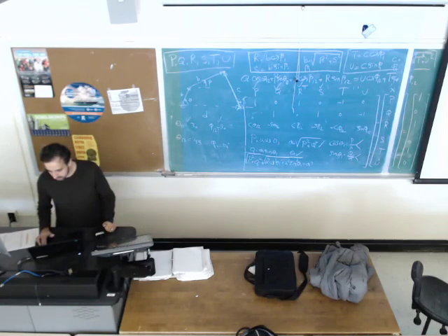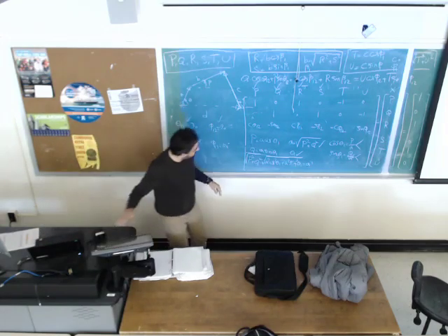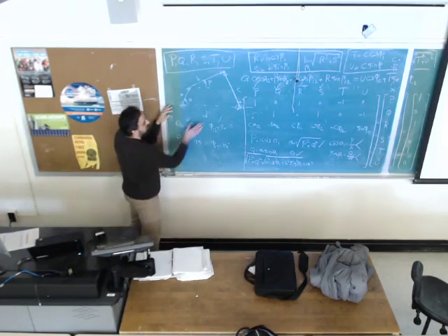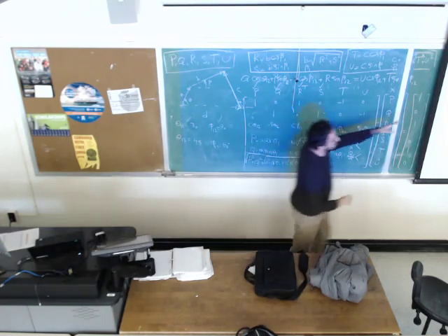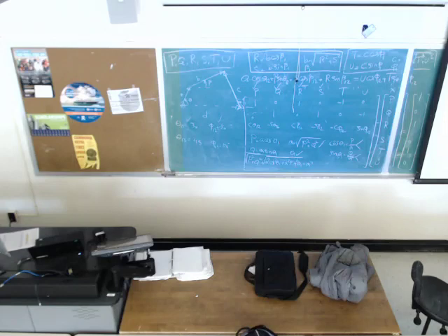So for this specific problem with this given desired task, theta 12 is 30, phi 12 is 90, theta 13 is 45, phi 13 is 120, you would like to design the mechanism. I pick three choices, beta 12 equals 25, beta 13 equals 30.